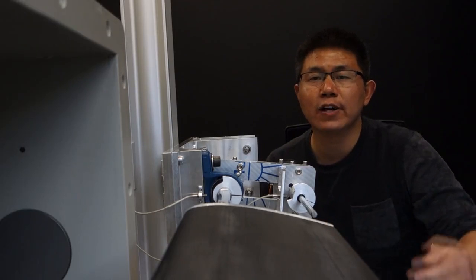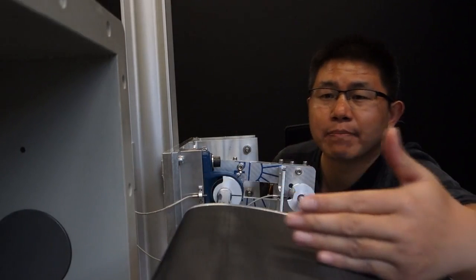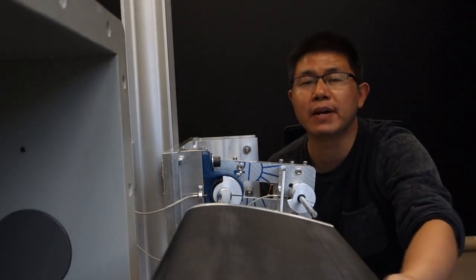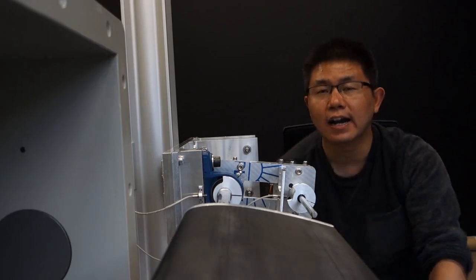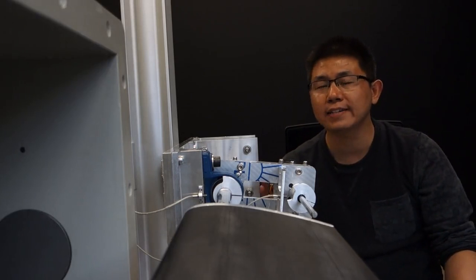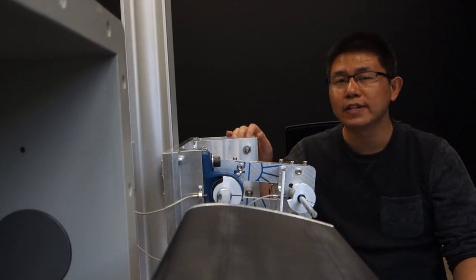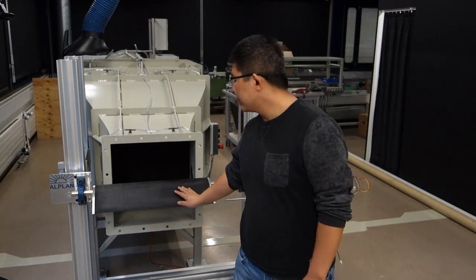I captured the flow field using two-dimensional particle image velocimetry with the plane in the middle span, and 36 pressure sensors buried inside are used to measure the surface pressure. I designed everything to be compact and portable, so I can just pack everything and do the experiment in another wind tunnel. In our experiment, we changed the pitching frequency of the airfoil.